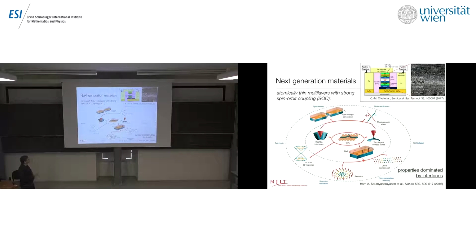Okay? And the second important effect that has recently attracted a lot of attention is the so-called spin-orbit coupling, which essentially is something that occurs when a ferromagnetic layer is adjacent to a non-magnetic heavy metal. And this produces an indirect exchange interaction between the spins of electrons in a ferromagnetic layer that somehow produce a tendency of spins to exhibit winding or rotations, spontaneous rotations. And this gives rise to a host of new phenomena, and the one that I'm actually going to be talking about is this so-called chiral domain walls.